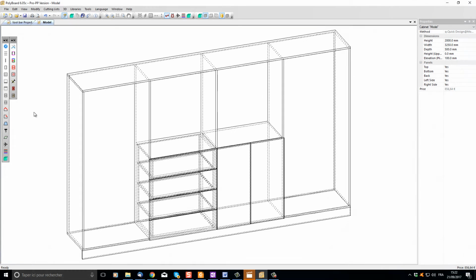In our last video we showed you how to use the Add Panels buttons in the Quick Design Cabinet toolbar. In this video I'd like to show you how to use some of the more advanced command buttons. The buttons 8 and 9 apply a library structure and delete the structure. They allow us to manage Quick Design Panel Structures libraries. Note that these buttons are greyed out until we select a panel.